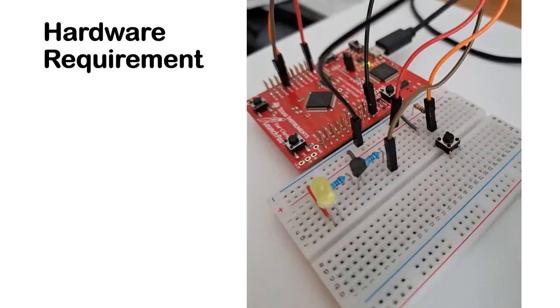Demonstration. So for this demonstration, you will need the Tiva C series LaunchPad board connected to the external LED and external push button switch circuit, which you should have built on a mini breadboard or breadboard. And you need to connect your Tiva C series to your laptop or desktop.